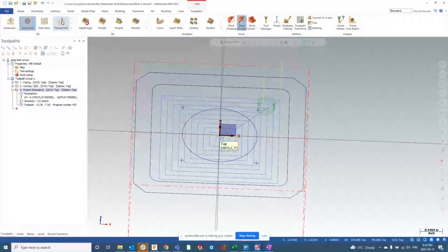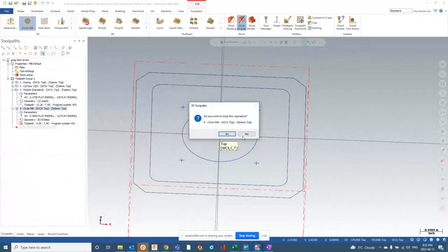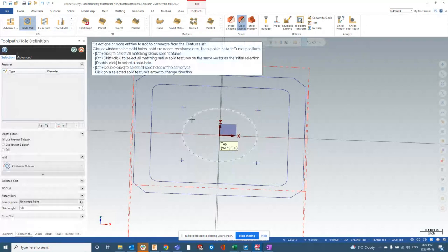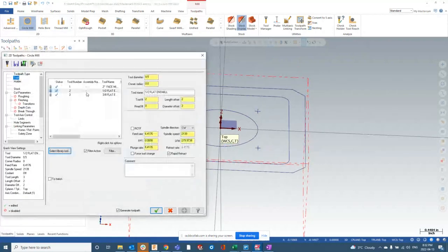Okay, next, circle mill. Circle milling, I really like to see 1/2 inch end mills because anytime you're not limited to the tool, just use a 1/2 inch end mill because they just are really good. You got a certain length with it. So tool, we're going to go back to our 1/2 inch end mill again, speeds and feeds. In this case, though, let's pretend that this is 12. I'm just going to make up numbers.